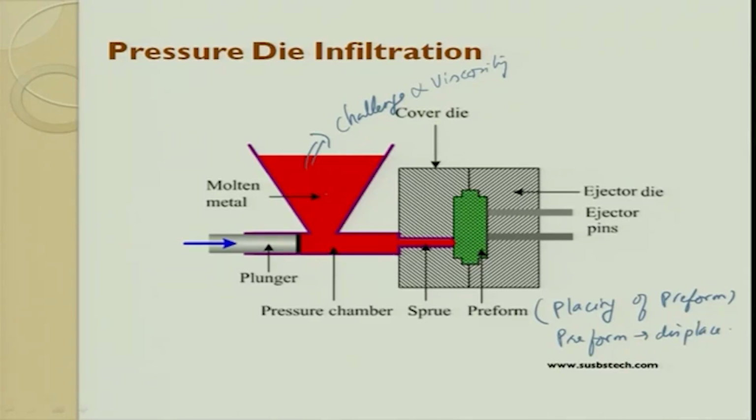So what people have started doing, like in casting, is adding spacers, which are again a ceramic material, and they later become an integral part of the component. Once they are an integral part of the component, they stay there for the rest of its life, so we have to choose a proper spacer. And these are the ejecting pins for removing the components freely as and when they are made.